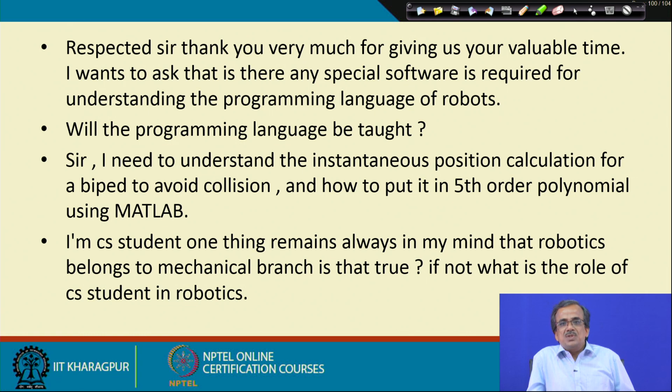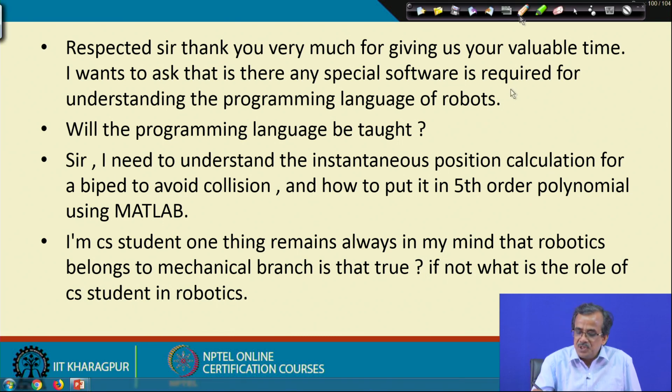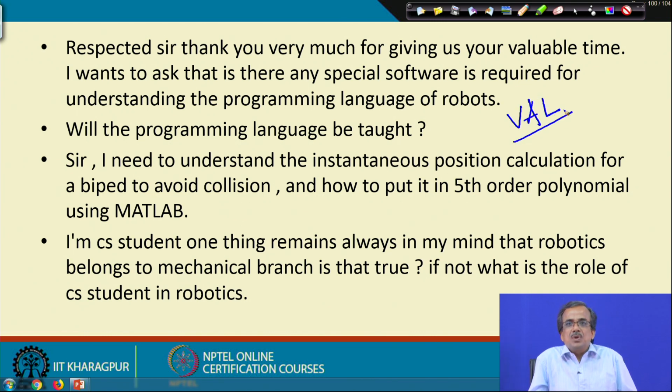The answer is, I should say, partly yes. For example, you might have heard about VAL programming, versatile assembly language programming, which I have already discussed in my lecture. This VAL programming, the versatile assembly language, is suitable for the Puma series robot. Some of the VAL commands are similar to the basic commands, and BASIC is nothing but the Beginner's All-purpose Symbolic Instruction Code, a programming language. So, some of the BASIC commands we have copied here in VAL.